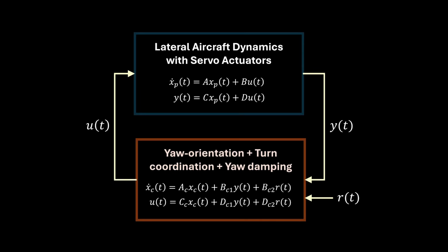The fact that many control system architectures can be put into these forms enables us to develop and use common tools to form things like loop gain transfer functions, return difference, sensitivity, closed loop systems, all conveniently for performance and robustness analysis, as we showed in this lesson.